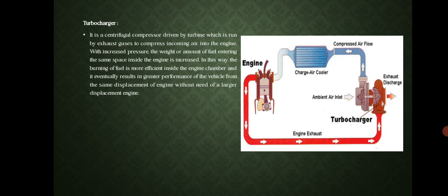Turbocharger. It is a centrifugal compressor driven by a turbine which is run by exhaust gas to compress incoming air in the engine, which increases pressure. With increased pressure, the weight or amount of fuel entering the same space inside the engine is increased. In this way, the burning of gas is more efficient inside the engine chamber, and this eventually results in greater performance of the vehicle from the same displacement of the engine without the need of a larger displacement engine.